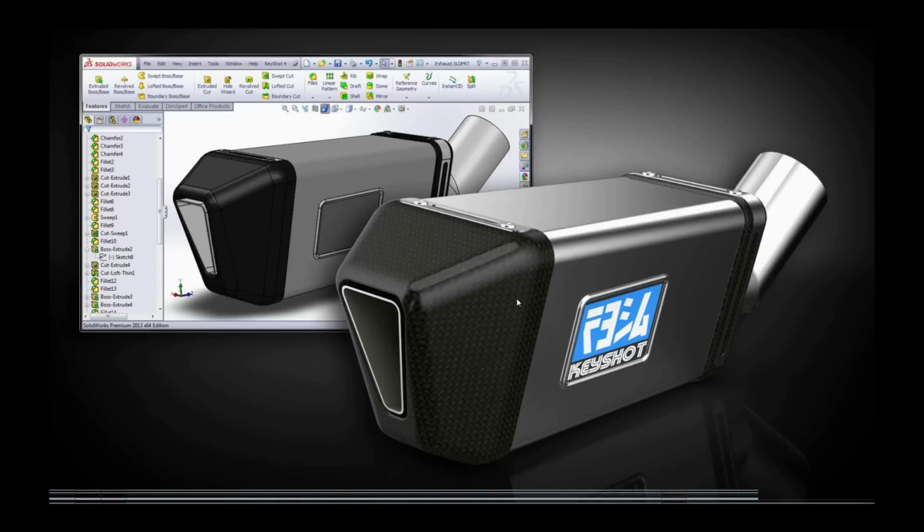So when live linking is used correctly, you will not need to reapply any of the materials that were previously applied to your model. The shaders that you've applied in your modeling software will be remembered by KeyShot, so the corresponding materials will automatically be applied. So when using live linking correctly, it can really boost your efficiency and your productivity when working between CAD and KeyShot.